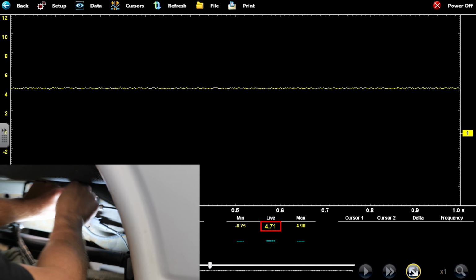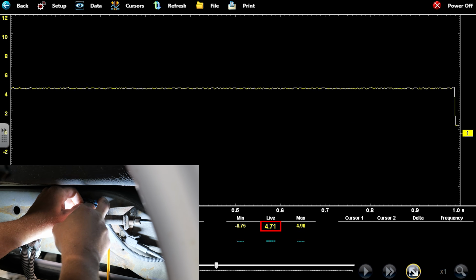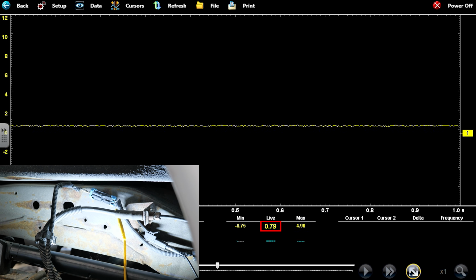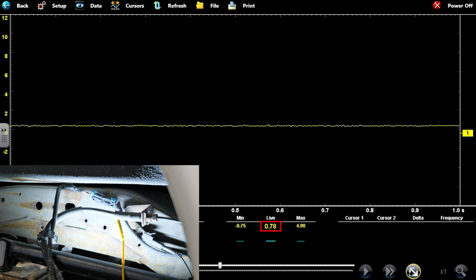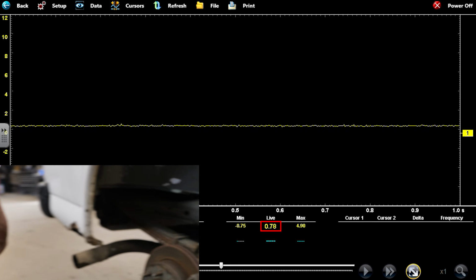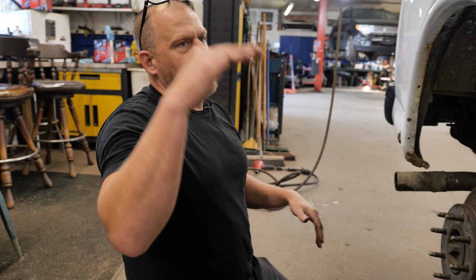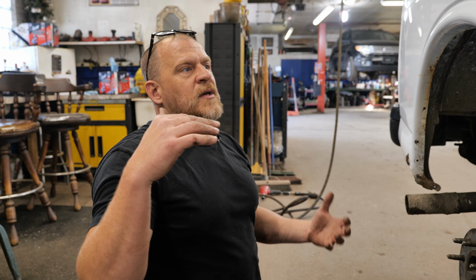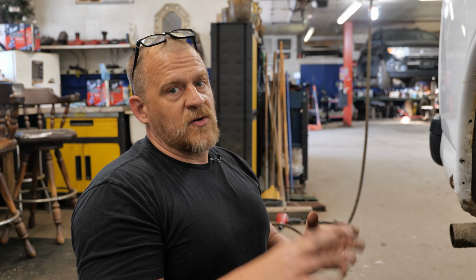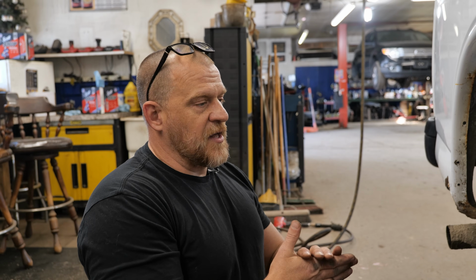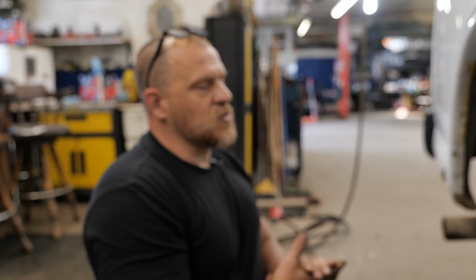Plugging this back in, you're going to see this voltage drop, right, to 0.7. There was that 0.7 of a volt that I wanted to see originally. The other side's 0. So it's dropping that bias so that it's really inside the computer. I have lessons on this too, by the way. This would be chapter 21 material on my website, ScannerDanner Premium, in the classes I teach at the school.